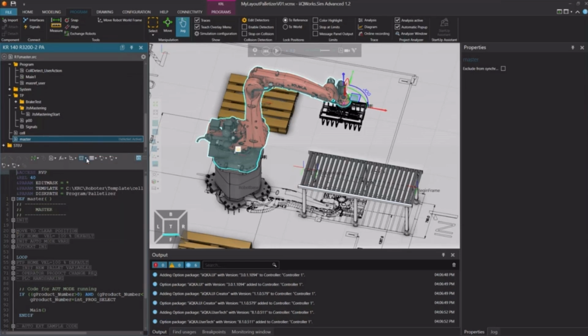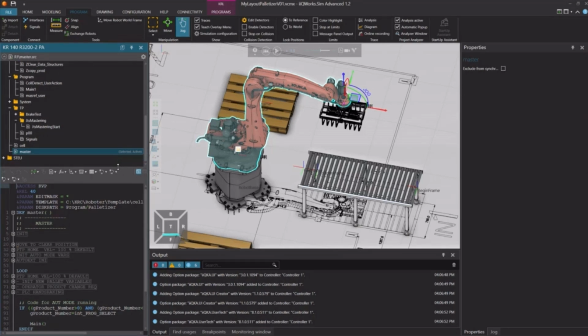After activating the master program, errors are expected. A common issue occurs in DAT files due to deprecated motion parameters. One frequent problem is the presence of velocity values in DAT files. These parameters are no longer required and will appear as errors. A regular expression is used to quickly locate and remove all velocity entries from the DAT file.